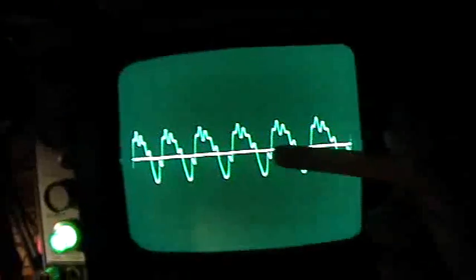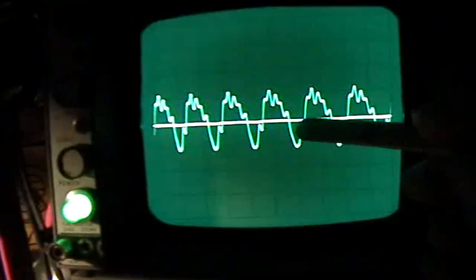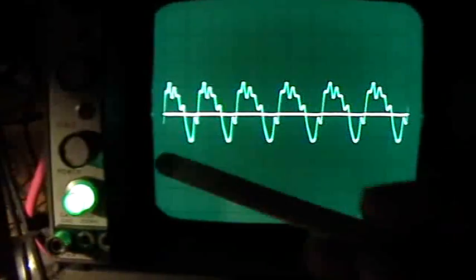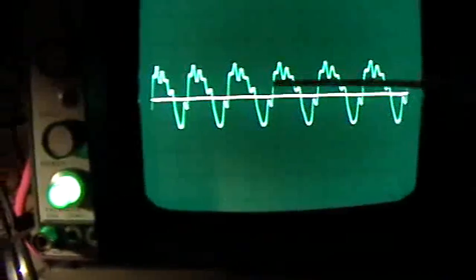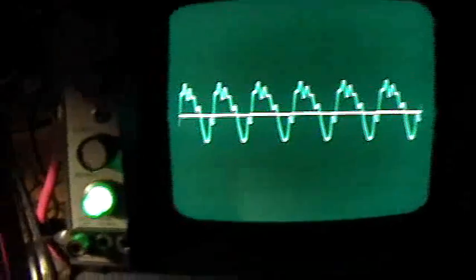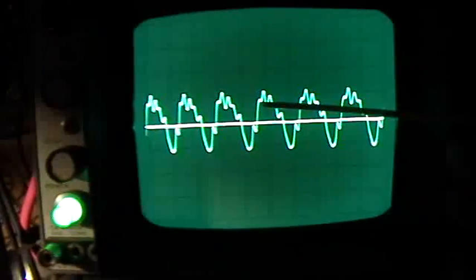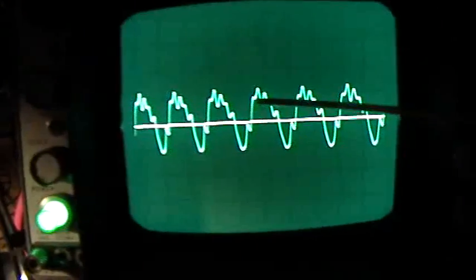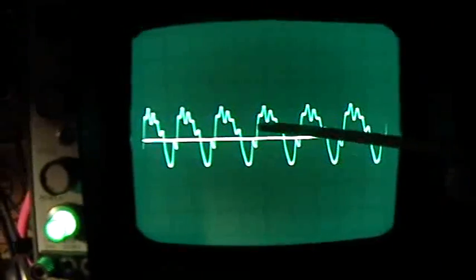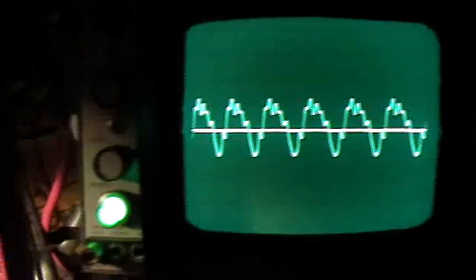All right. So now it certainly looks to me like there's more area in the peak above than there is in the area below. So just roughly guessing, I would say that if I integrated this trace over time, I would see what would correspond to a positive energy flow, not a negative one. In other words, energy is flowing out of the battery, or in this case out of the 555 timer supply in these oscillations, and is going mostly around the circuit in the correct direction.